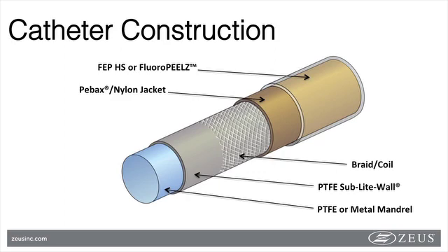In more complex catheter construction, such as cardiovascular or neurovascular, this critical step works twofold, not only bonding to the PTFE liner, as previously mentioned, but also allowing a smooth transition between the multiple durometers along the catheter shaft. This is the industry standard and has been since the emergence of cardiovascular catheterization. Advancements in minimally invasive surgery have led to more complex procedures requiring lower profiles, softer durometers, and smaller diameters.